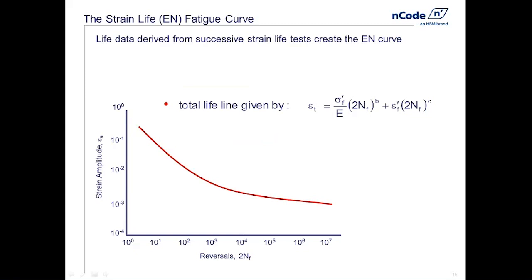Notice that this curve, the strain life curve, has a band, or non-technically you may say a knee, in the curve. This goes to show the difference between low cycle fatigue and high cycle fatigue. Stress life only works for high cycle fatigue because even though it was inherently tracking not strain, but the wrong thing, stress, it gets it right when stresses and strains have a scalar relationship, and that's before yield, and that's high cycle fatigue.